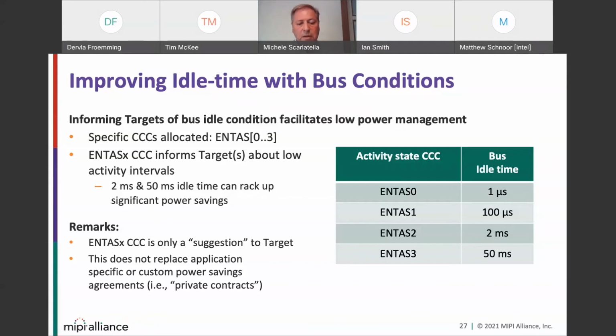You can really put things in idle mode, and you can save quite a bit of energy there. Just a note: the activity state is not a must, it's a suggestion. So if a target needs to stay awake for some reason, it still can. But if it does not have anything peculiar in place, it knows that the controller will not do anything and it will go to sleep for a certain period of time.